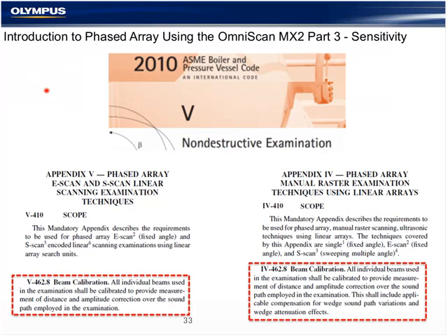Our codes and procedures are very clear about inspection sensitivity. It's directly related to the reject rate that was designed by the code. Little holes produce a very sensitive inspection with lots of rejects, typically, where big holes are a less sensitive inspection that would allow more flaws. Depending on the code, the sensitivity of the inspection could be very different. An AWS fabrication weld could have flaws that are not permitted in a closure weld for a pressure vessel or piping.